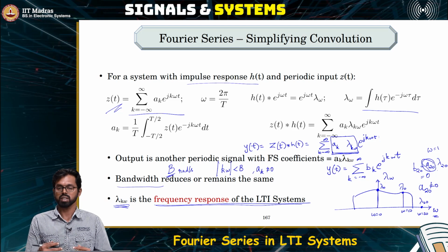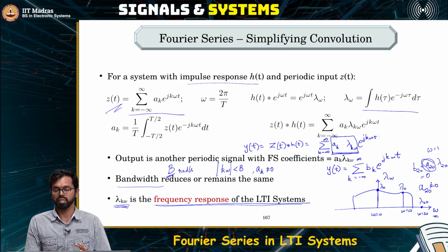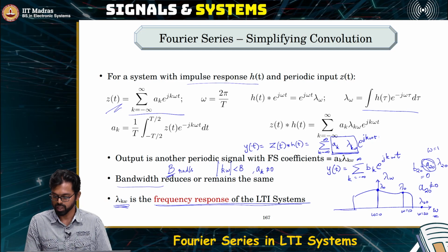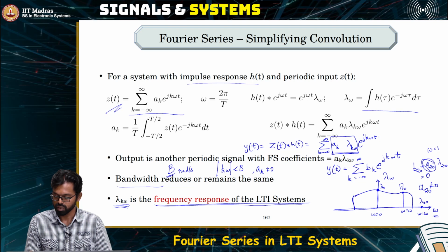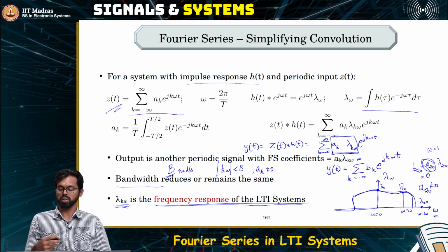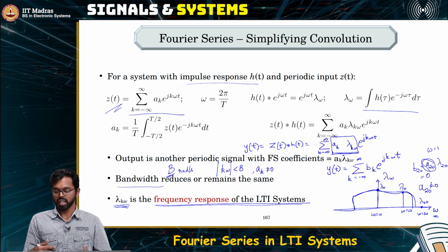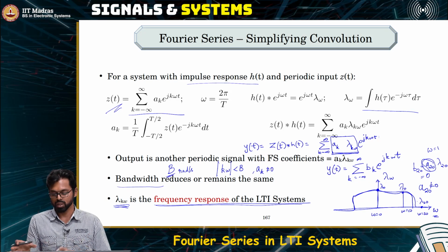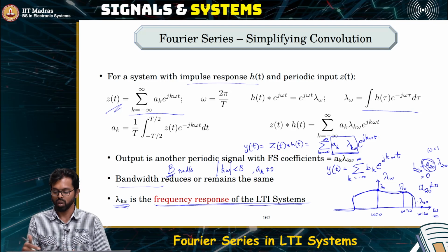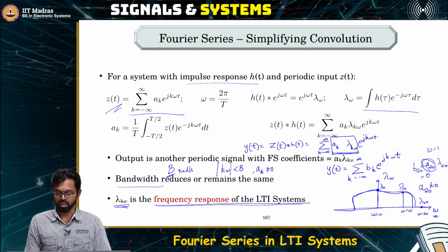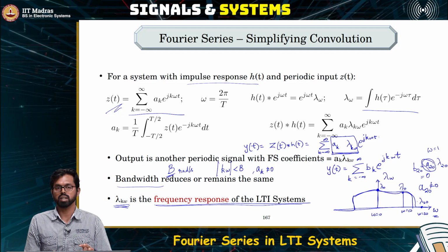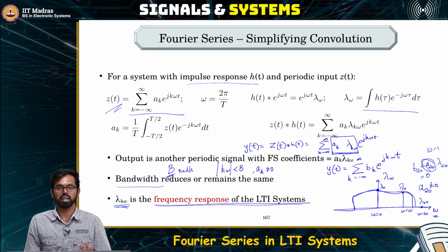So, this gives us an idea of how to identify or characterize filters. If I plot the frequency response of filters, from this frequency response I should be able to say that my LTI system is going to filter out these frequencies. It is going to attenuate this much frequency by this much, or it is going to amplify this much frequency by this much. So, this becomes a very important tool to analyze circuits and filters and their characterization.